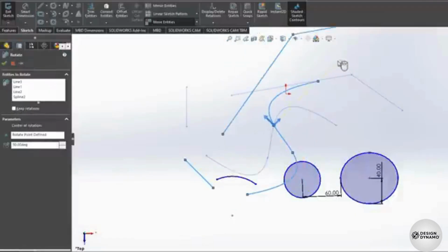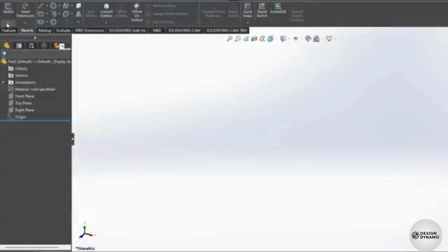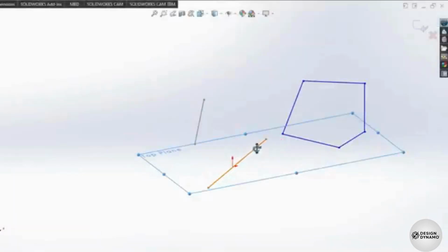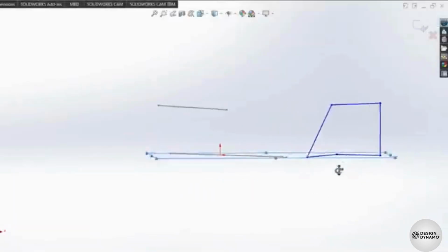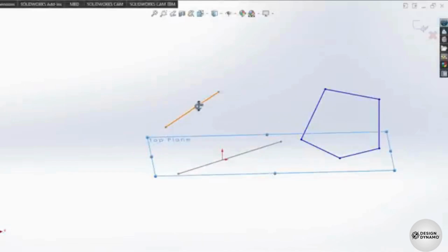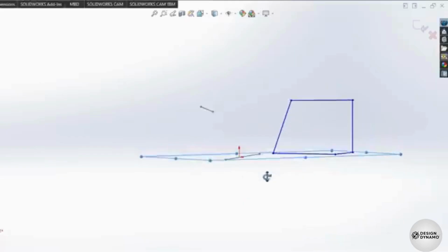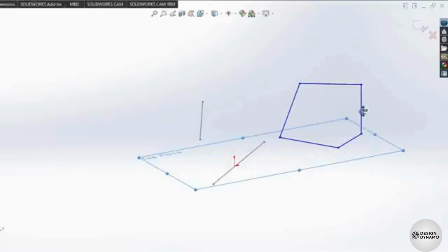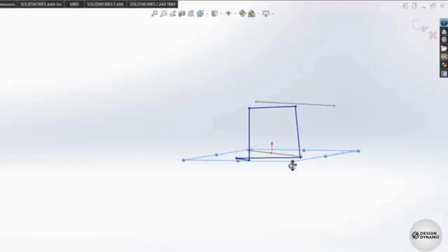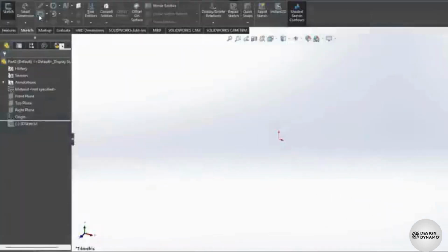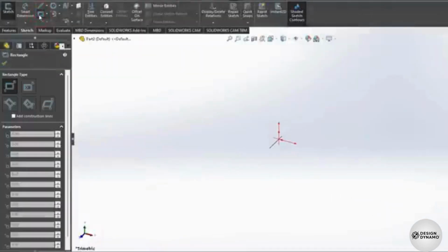work as expected. Besides 2D sketches, you can drop 3D sketches to draw 2D entities in a 3D environment. These differ since 2D sketches physically lay on a single plane, whereas 3D sketches can be parallel to any plane or even spread towards multiple planes. The way to draw 3D sketches is identical to 2D ones, enabling any drawing tool and selecting the right plane.